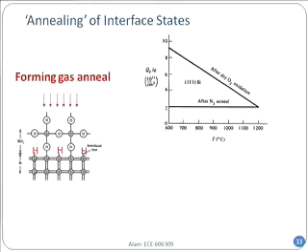The temperature you see here in degrees centigrade is 1100 or 1200 degrees C. And that will give you, look at the plot, about 2 times 10 to the 11. Here you have not yet done this hydrogen or forming gas anneal or the passivation, not yet, but you still have about 2 times 10 to the power 11 even when you anneal it at 1200 degrees C.